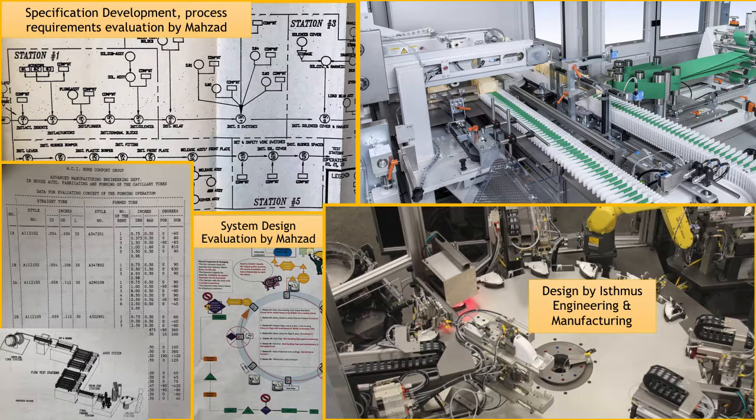How accurately to make the adjustments, the accuracy, the frequency, and all this variation need to be identified before designing the equipment, because the machine designers have a choice of doing this automatically or manually, and how they design these features depends on the application, accuracy requirement, frequency requirement, and company capacity requirement to do the adjustment. Based on that, the feasibility will say, okay, you have to fully automate this, or you can leave the changeover between models to operators.